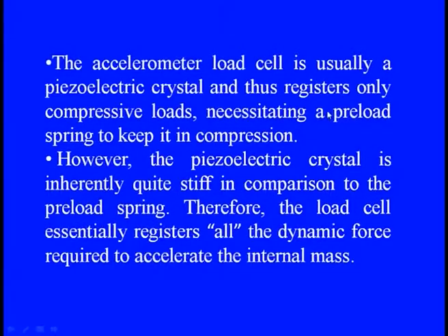The accelerometer load cell usually has piezoelectric crystals registering a compressive load, which necessitates a preload spring to keep it in compression. So, we have the spring and the damper, on which the mass is always kept in the compressive, or preloaded, state, and the piezoelectric crystal is inherently quite stiff in comparison to the preload spring.